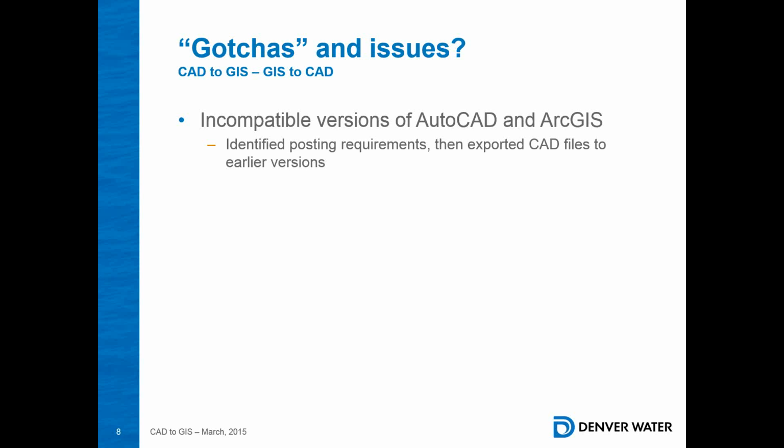Right. No, it's not. And then also, to piggyback off that, is Civil 3D. We don't send intelligent objects to our asset recording group. So if we're using Civil 3D, when I mention these specified customized layers that have ARG prefixes, we're only sending basic AutoCAD features: blocks that are attributed, line work, and polygons. We don't send text. We don't send any kind of intelligent objects. A does not equal B.